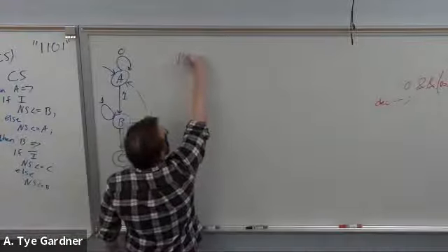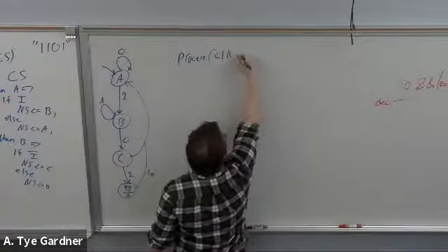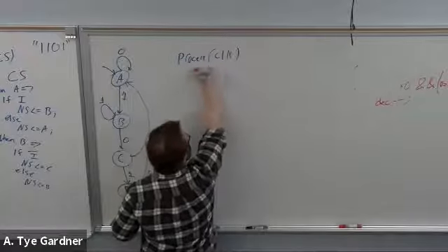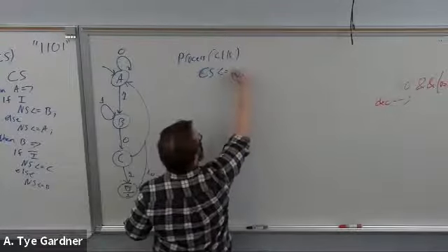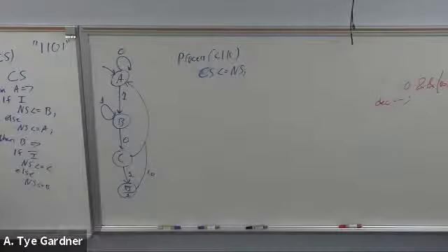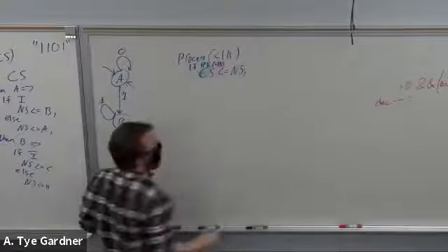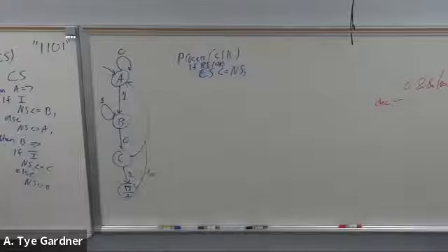Well, that's easy. We just say process on clock, let me do it this way. Current state equals next state. Done. That's the register, right? Because each rising, oh, almost forgot. If RE on clock, right? Because otherwise I've messed up, and we'll do it on both the rising and falling edge. So there we go. Clock happens.